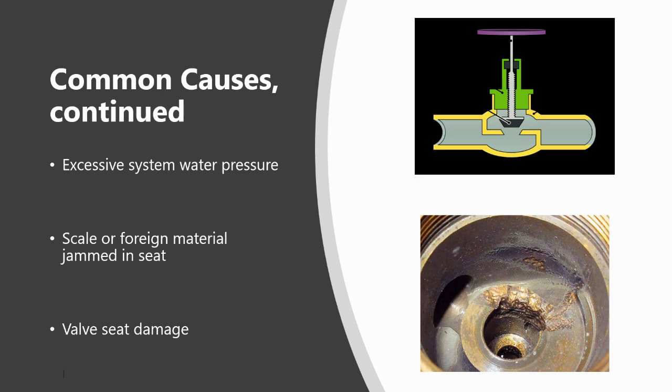A form of valve seat damage called wire drawing causes a lot of persistent valve leakage issues. It's essentially an erosion or pitting of the valve seat, which makes it impossible to seal off all flow. This type of valve damage can be caused by valves that spend a lot of time nearly shut but not completely shut, as the constant pressure drop across the valve will allow high velocity fluid to actually cut into the valve seat. So valve control signals that are not kept properly adjusted to fully seat and shut off all flow can allow continual leak by and eventually erode and permanently damage the valve seats.